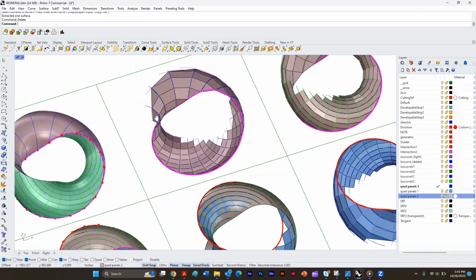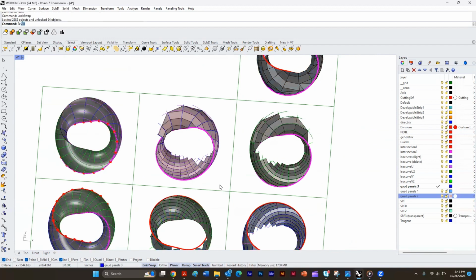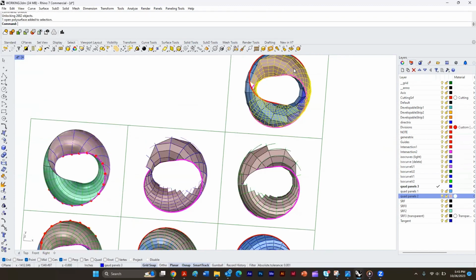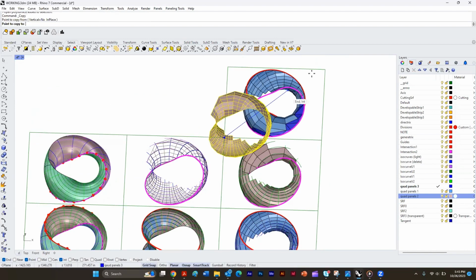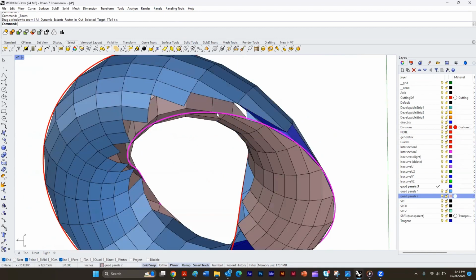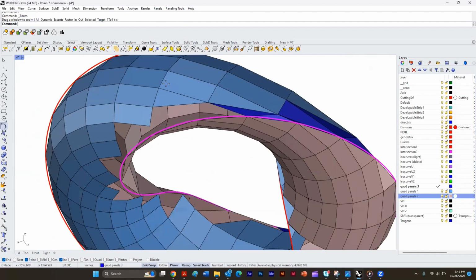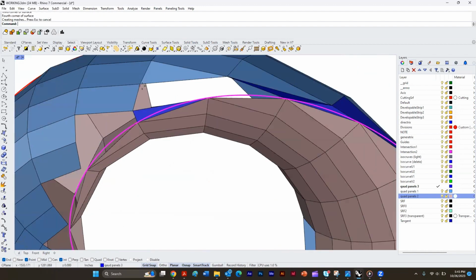Okay, so let's lock this, lock swap, cell surf, cell polysurf, join, unlock, delete that, copy this over there, and see if we can, yeah, now we're good. So I can keep going back, filling in this with triangles.